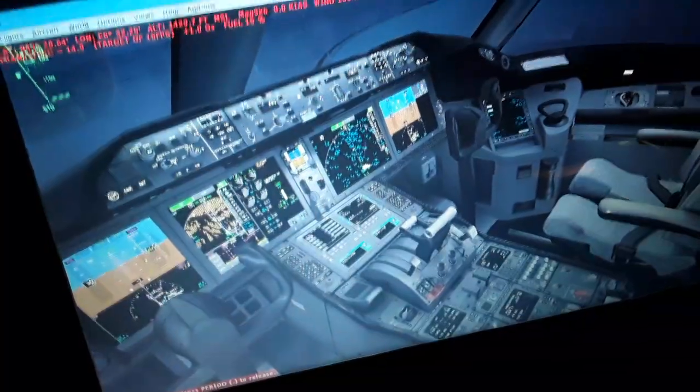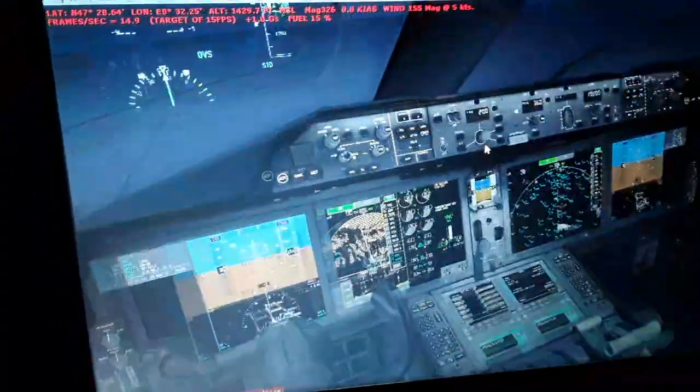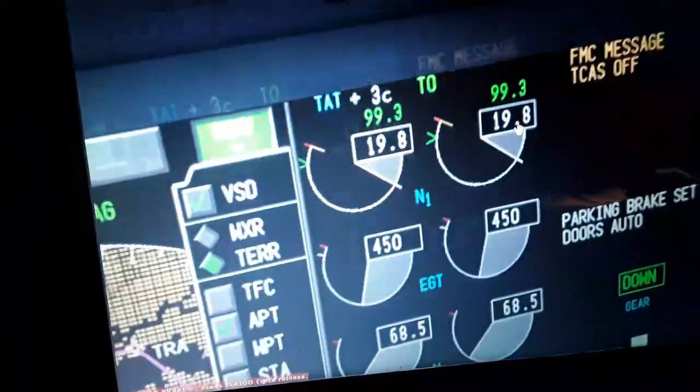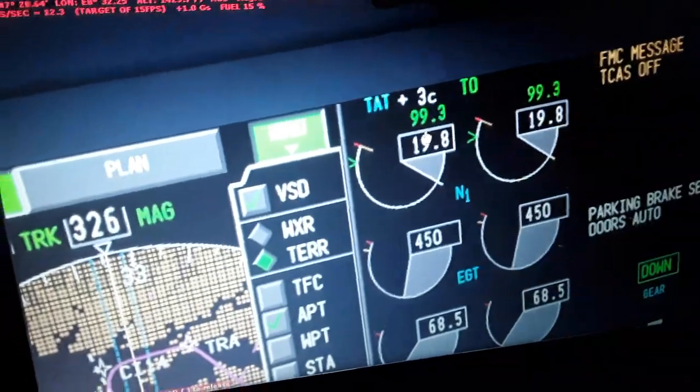We have a few more things to see. You can see the displays here, the engines, left and right engine display. You can see the N1, and I will talk to you about the FADEC. We have the FADEC installed in our Boeing 787-900 aircraft. The FADECs are the full authority digital electronic control computers. One is for engine gearbox, dual channel redundancy. When one channel fails, the other takes over, controls functions, and displays all the engine data.